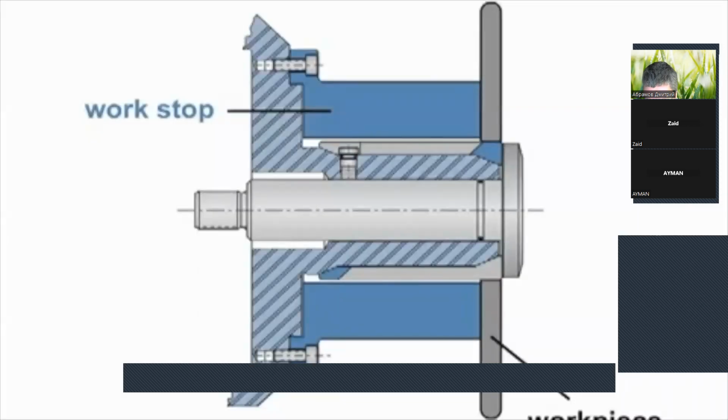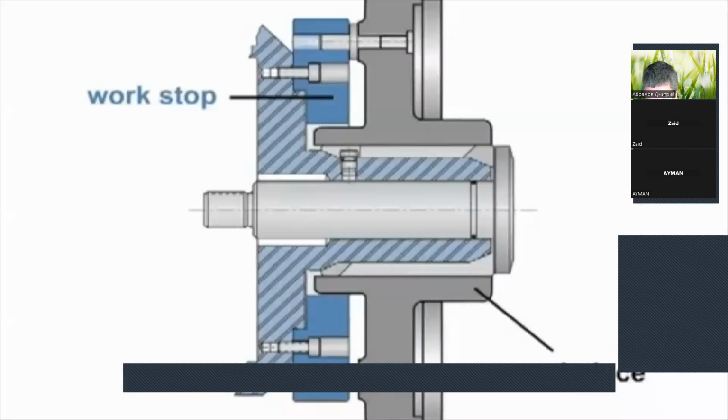This is an example of a short gripped workpiece using a dead length work stop to machine the part to a desired length. In addition, the work stop acts as a limit ring behind the part based on the short gripping length. When the workpiece is larger than the standard work stop diameter available, a custom work stop can be machined for your required application.